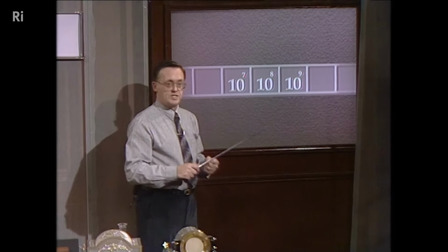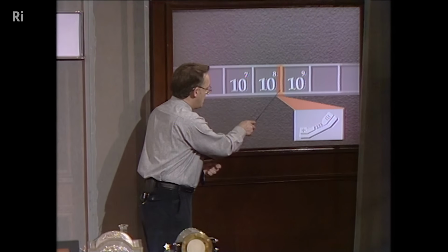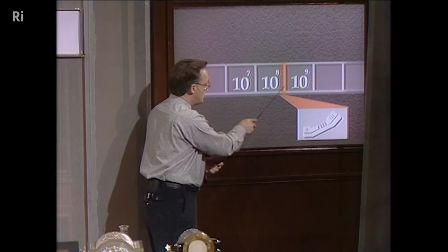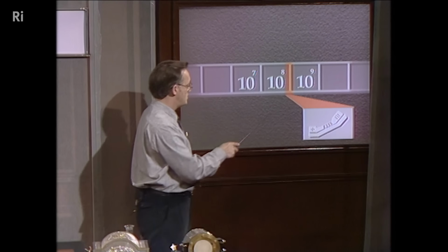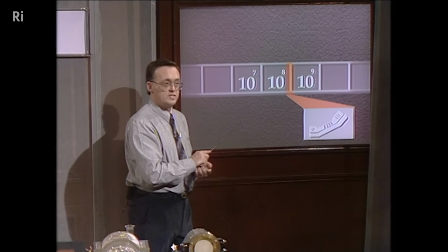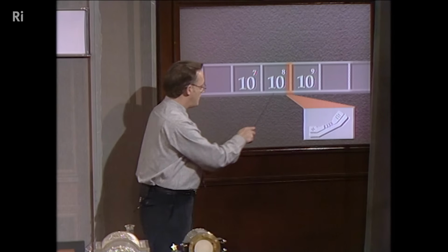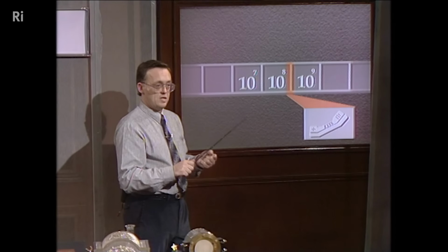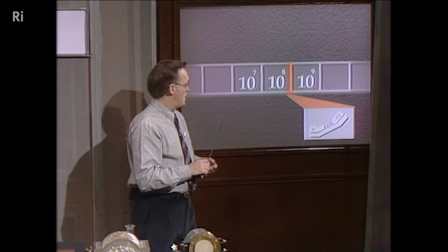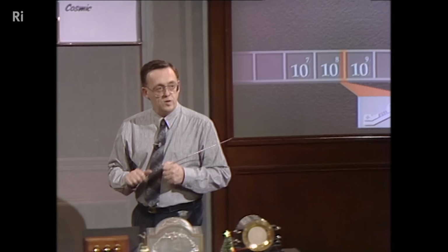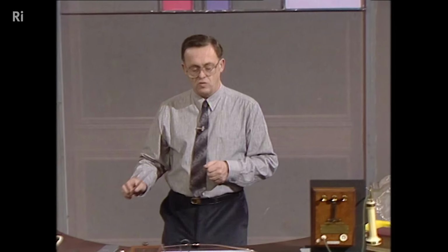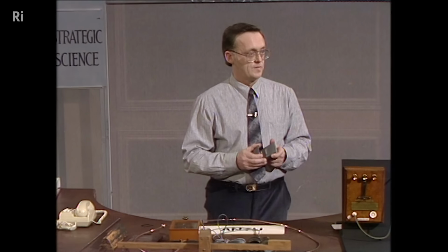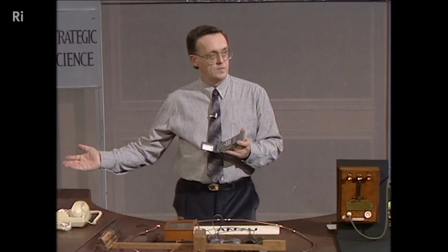What has been reserved for the CT2 phone is a special band just about here. There's 4 megahertz of bandwidth being made available between 864 megahertz and 868 megahertz. And that 4 megahertz will be broken down into 40 channels of 100 kilohertz each. And that will give ample scope for more and more people to have access to a cordless phone. So this here is a digital phone. This was an analog phone.